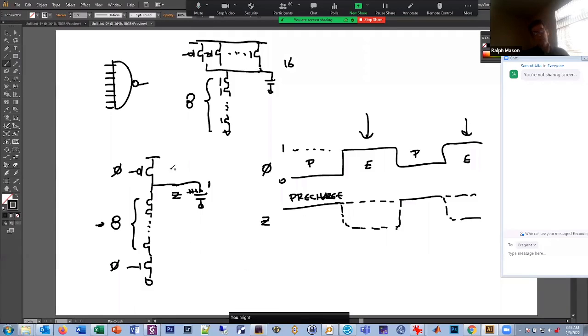You might ask yourself, well, why would I want to do this? Well, the obvious thing, or hopefully the obvious thing, is that we have a lot fewer transistors. Here we had 16, here we have 8, 9, we only have 10 transistors. And in fact, we can write an equation here. If we have some number n of N channels, we'll have 2 times n transistors here, because in standard CMOS or static CMOS, for every N channel, there's an equivalent P channel that's connected in the opposite parallel versus serial connection.